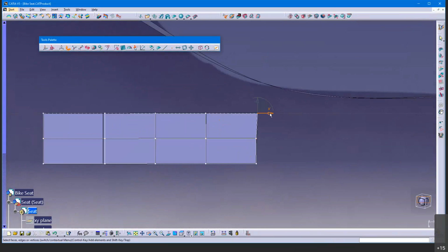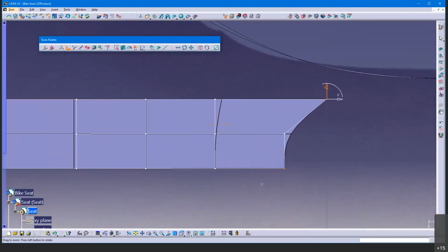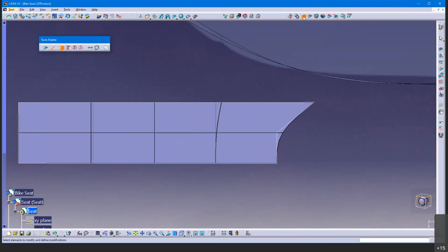I usually drag the wrong one here, but let's see what happens. So I'm going to drag this out. See how I'm dragging that out? And here's the trick. Here's the magic trick. I drag this out like this, and then I'm going to do an extrusion, the same extrusion, edge fill, using the control key. I'm going to extrude those together.